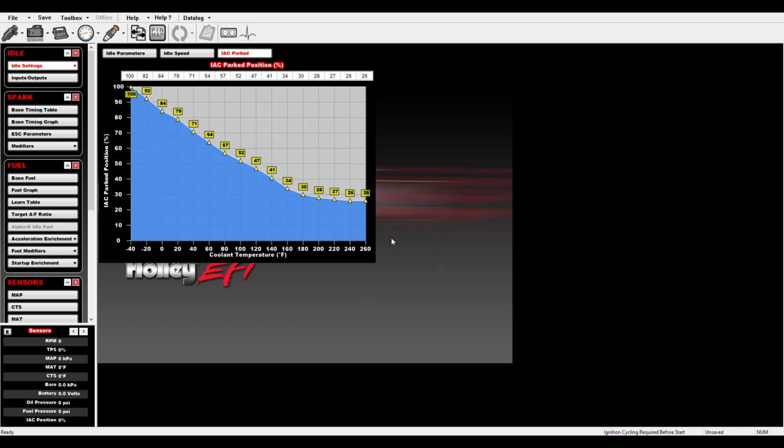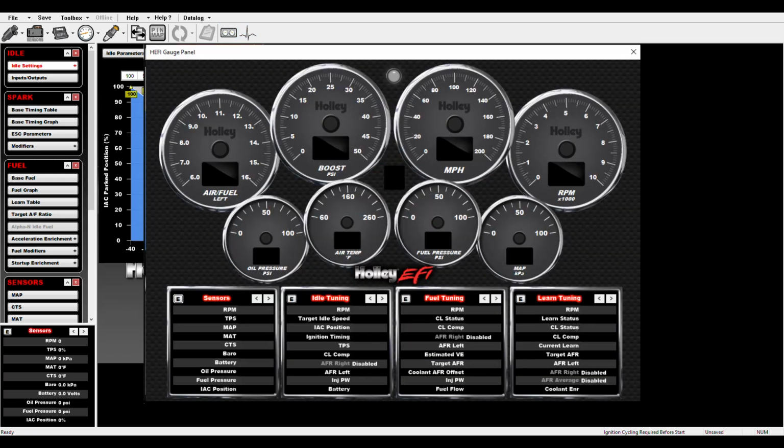You can pull up the gauge cluster here, and when you're plugged in, it will live spit out all of these parameters as the engine is running. So it's pretty neat. It's pretty powerful for tuning. Like I said before, because I'm only hooked up to a desktop and not a laptop, I can't do too much of this. I can play around with the RPM and some other stuff, or the fuel pressure, but can't do too much.